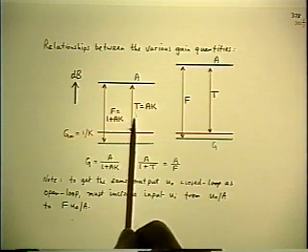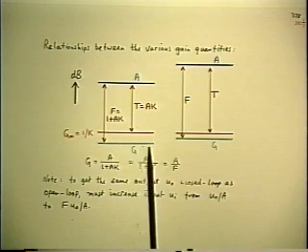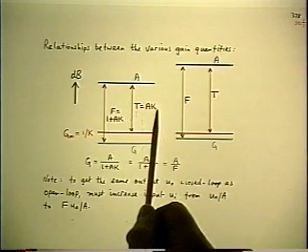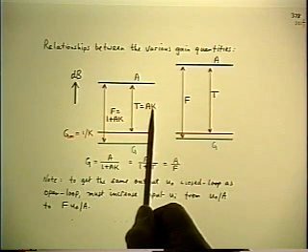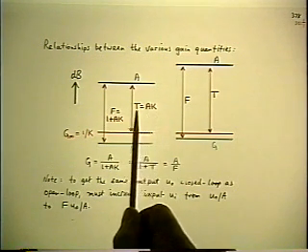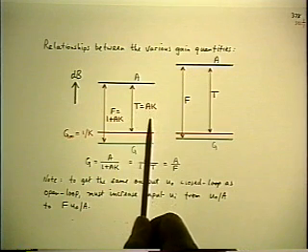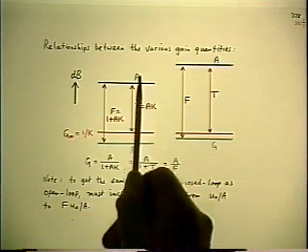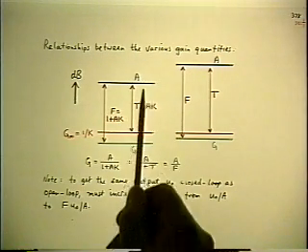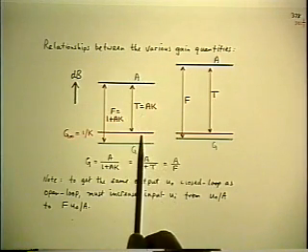Now the geometric relationships between those quantities are T is A times K, but K is 1 over G infinity. So T is A over G infinity, which is a ratio, but on the dB axis that means T is equal to the dB difference between A and G infinity.